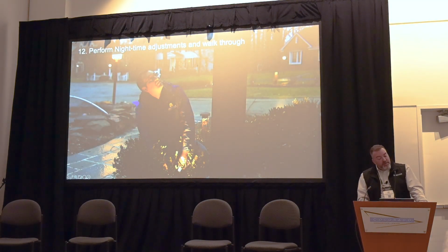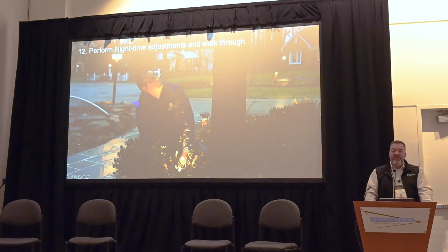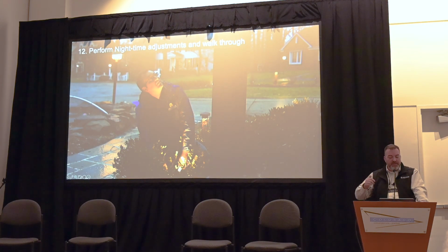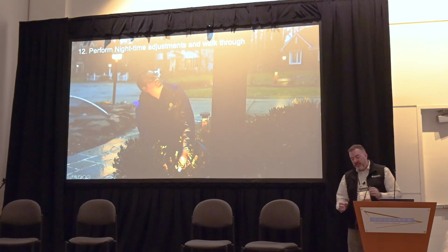And then very, very important, make sure your tech is available to go through and do night aimings. Just installing lights isn't enough. You've got to be there to aim the lights. That's a much younger version of me. So Tech 1, use your lead tech. If you're going to need to go out and aim in trees and move things around, you don't want the designer doing that, because once he's out there moving lights around, he's going to look into that light source.